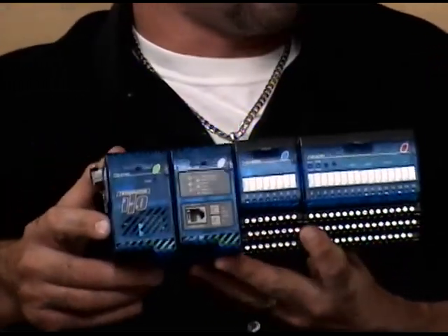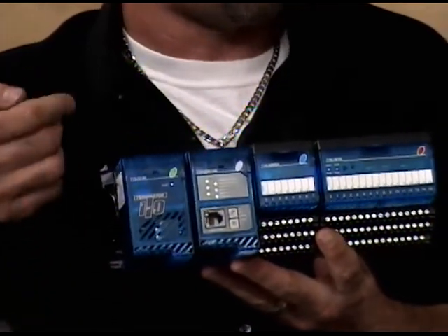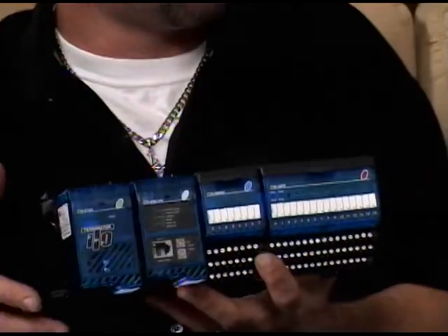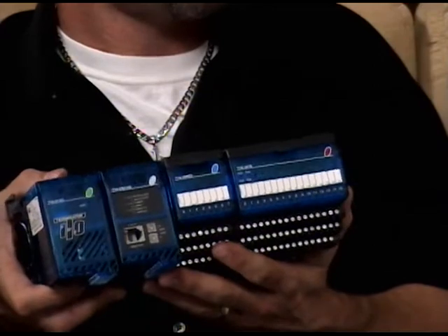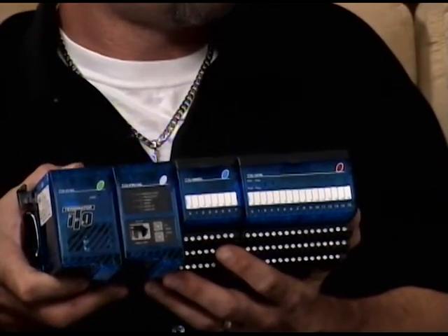Right. The EBCs, we offer those in flavors of the 205, the 405, and the Terminator. So yes, an ERM, an Ethernet Remote Master, we make those in 205s and 405s. An ERM can talk to a 205, a 405, or a Terminator, or all of the above at the same time. You can use all of those out in your rack. And again, everything's interconnected with relatively inexpensive Ethernet type cable.